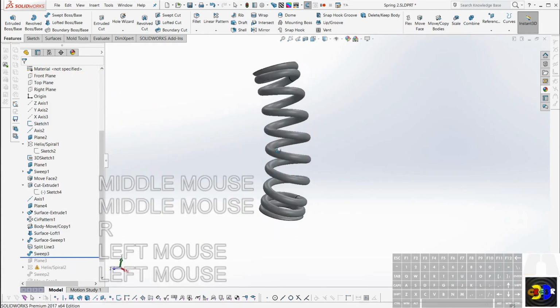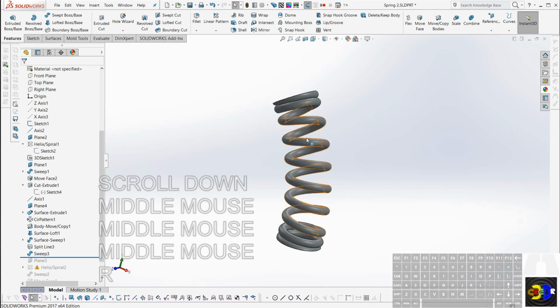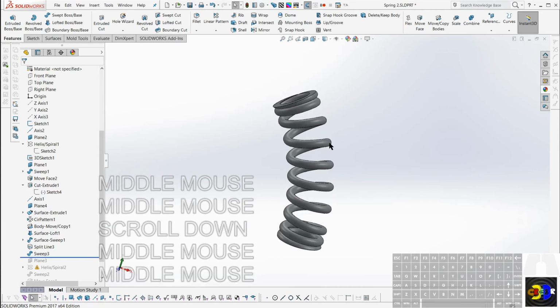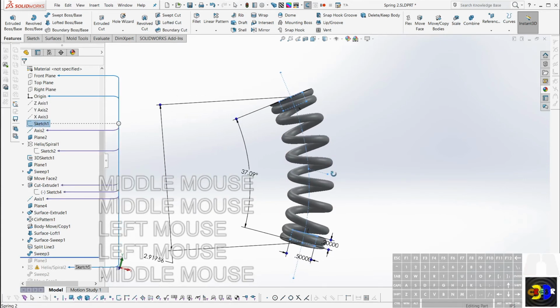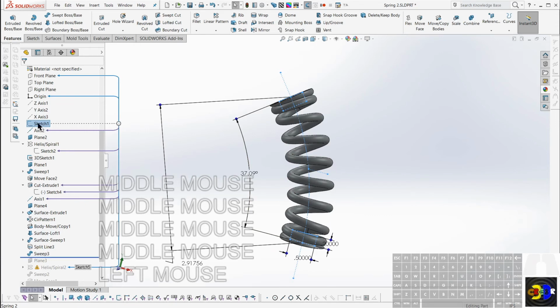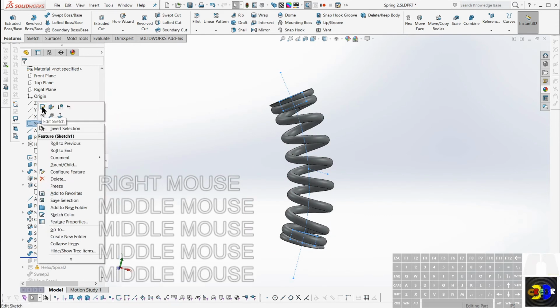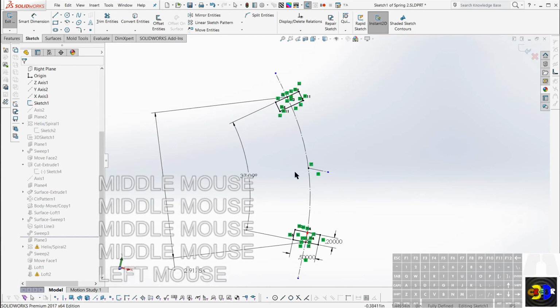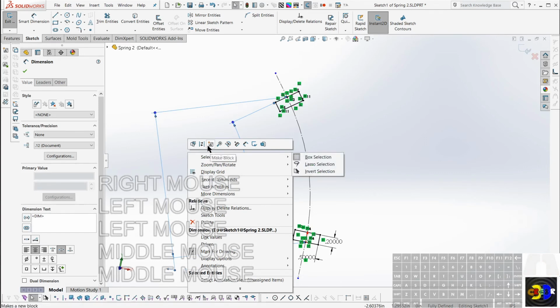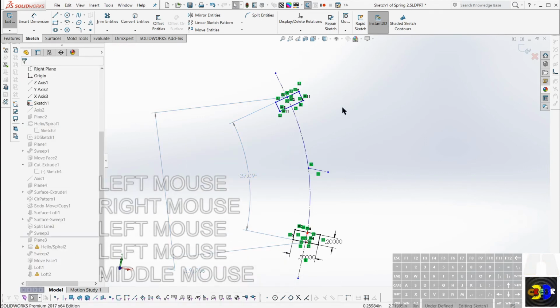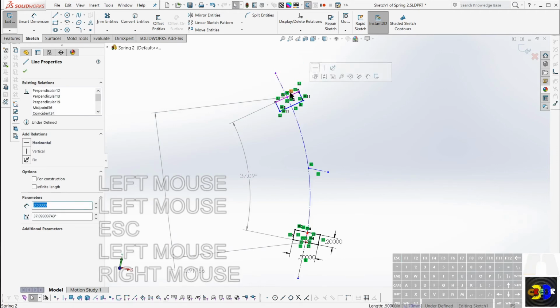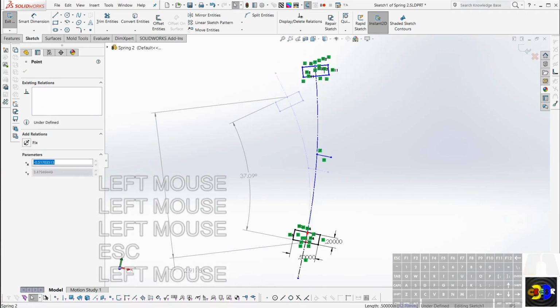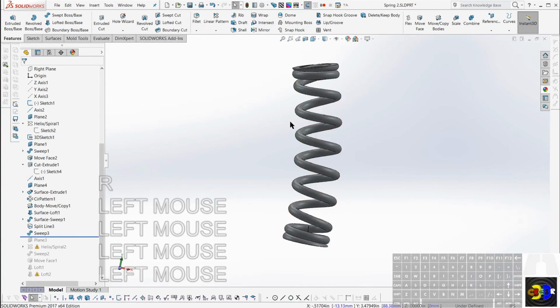So let's say if this was in a pair of pliers to hold it open, or any application like that. So now you can see that I can have excellent control over this. And you know what I actually could do is, if I wanted to align these to something in an assembly, I could make these numbers driven, and I could just drag these around, rebuild. I could turn that sketch on, drag it around.